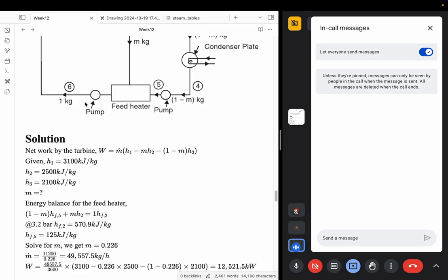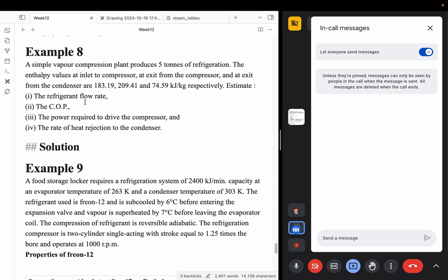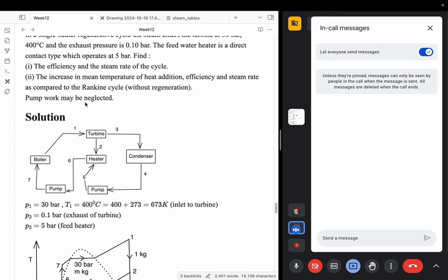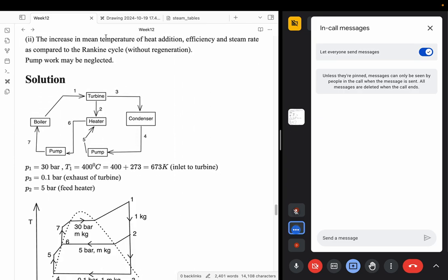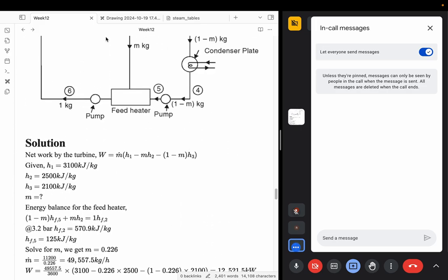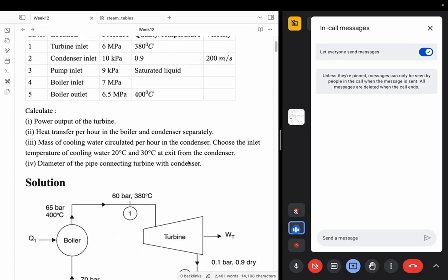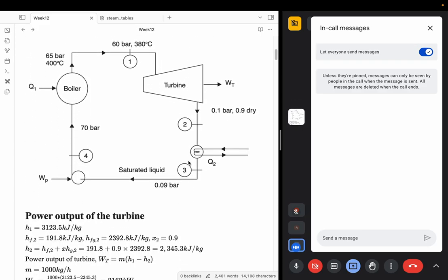Okay, I didn't solve a Brayton problem. I'll put that. You are now talking of the vapor compression cycle. Yeah, depending on your temperature and pressure, right? Brayton is a gas cycle, it's just air, just gas. So at the temperatures and pressures at which you are operating, it is completely in the gaseous phase. You don't have a two phase thing. It depends on the pressure and temperature, right?